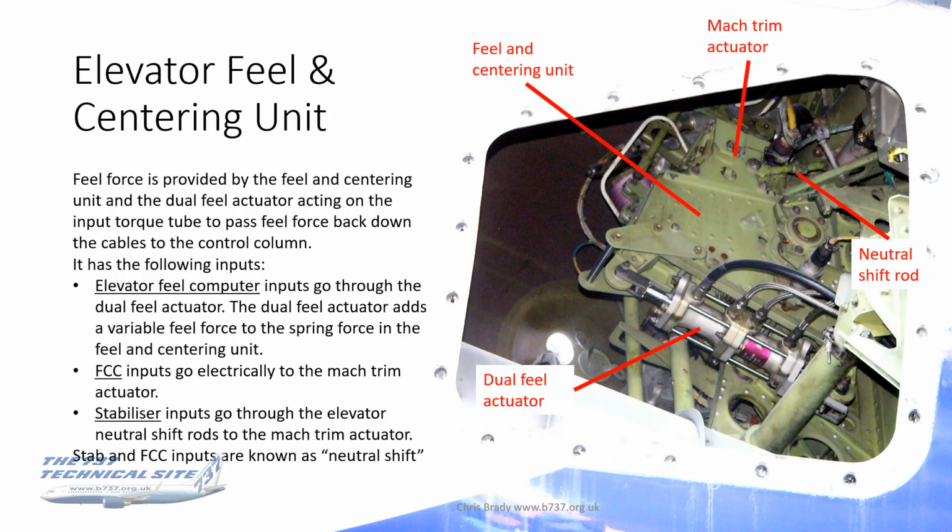So it's elevator feel, which is all of the three inputs from the elevator feel computer, and then inputs from the FCC and the stab, which are for centering, which we as pilots know as neutral shift. So let's dissect neutral shift.